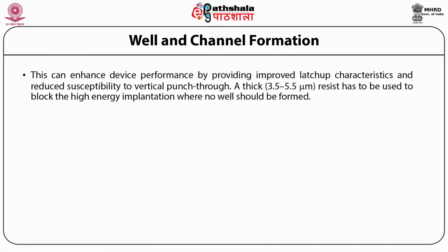This can enhance device performance by providing improved latch-up characteristics and reduced susceptibility to vertical punch through. A thick resist, that is 3.5 to 5.5 micron, has to be used to block the high energy implantation where no well should be formed. Thick resist and deep implants necessarily lead to fairly coarse feature dimensions for wells compared to the minimum feature size.